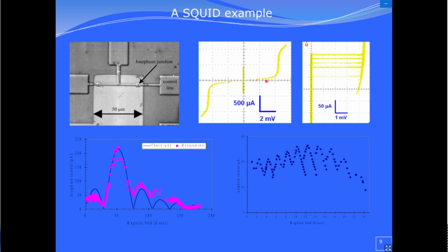And when you do this measurement, you observe this IV curve. It's a screenshot of an oscilloscope, as you can see. This IV curve is maybe not exactly from this device, I see, because here are 4 millivolts but here there is just one junction, whereas here there are two junctions in series and two in parallel. But anyway, you see clearly the Josephson current, with IC, the maximum current, which is the Cooper pair current.